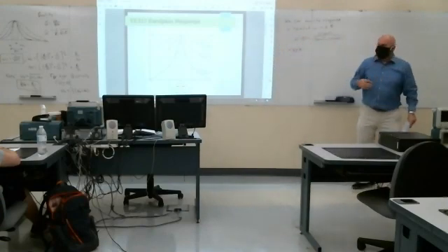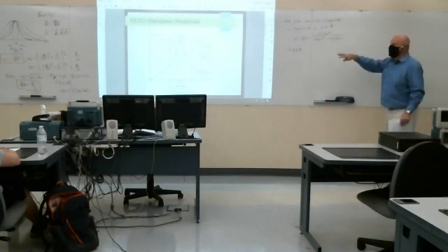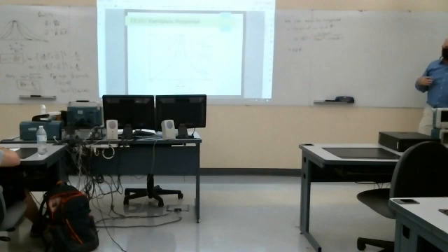Okay, so that was a second order bandpass filter. Second order because in this particular case, the denominator's second order. If it's a ratio of first order terms, or if the highest order, either the numerator or denominator, is first order, then it's a first order filter. These RLC circuits will be second order filters.